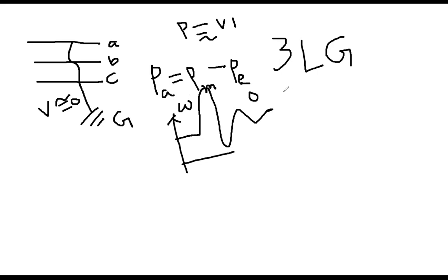And then next is 2LG. It is called double line to ground. What is the example? For example, 2 phases got shorted and then grounded. For example, I am drawing the other side, although this is the above side, then let's assume that this is the grounding. So this is the example of 2LG.